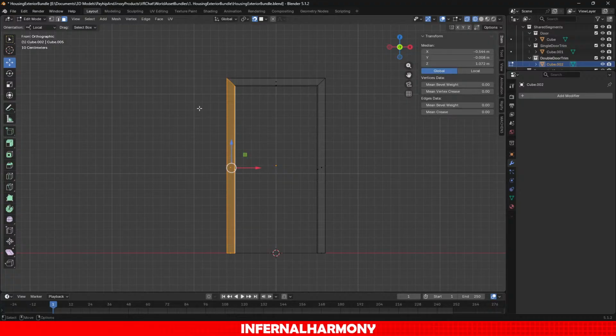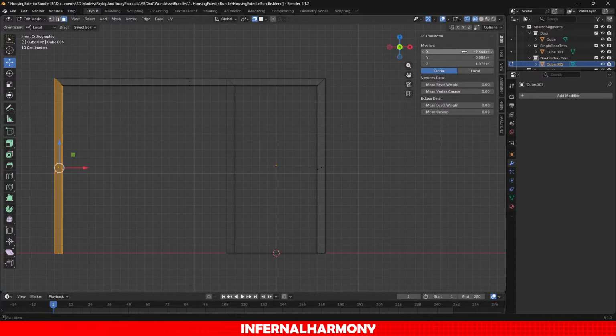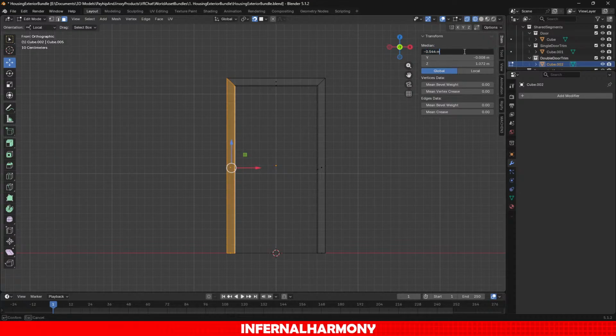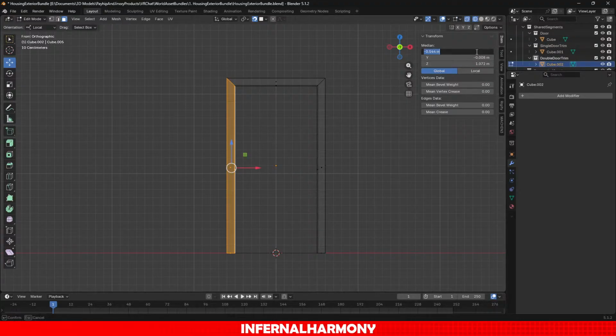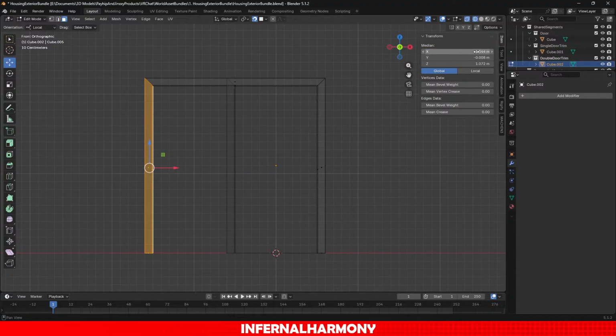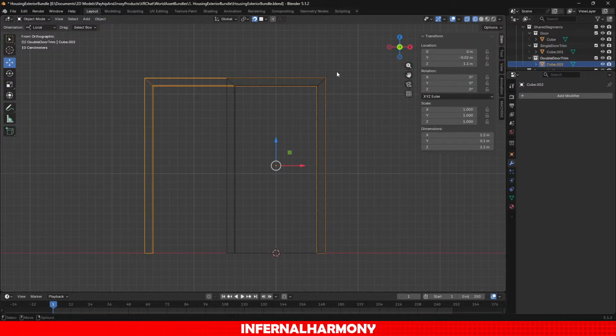I want to go ahead and grab these faces. That's the median. Then with the median, I can, let's say, yeah, it would be subtract. I think that's a bit too wide because I grabbed the wrong attribute. That's why. It's just 1 meter wide. In that case, I just -1. There we go. Now, in theory, that should maintain the thickness of the frame. As I said, in theory.